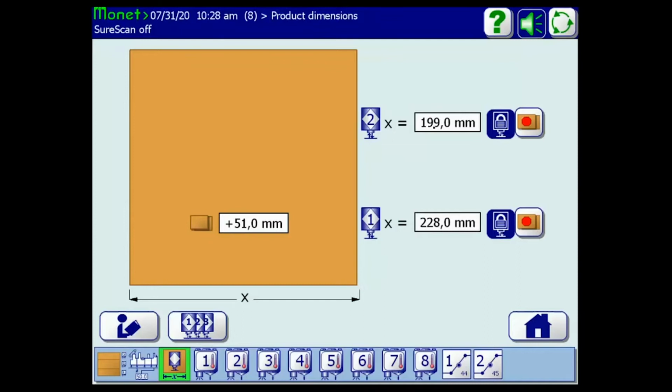We reference the lead edge of the carton to do all of our gluing and detecting per piece. Okay, so if the system is registering multiple lead edges because of openings or cutouts in the product, you won't be able to glue and inspect all of the events you're trying to program. So therefore, again, it only applies if the trigger falls into an opening or a hole on the product, you can lock that trigger and manually enter the length.